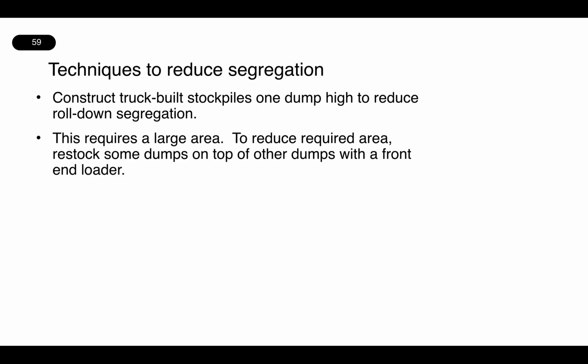So there's techniques you can use to reduce that segregation. Truck-built stockpiles and one dump situations can reduce roll-down segregation. Requires a larger area, and to reduce the required area, you can restock some dumps on top of other dumps with a front-end loader.